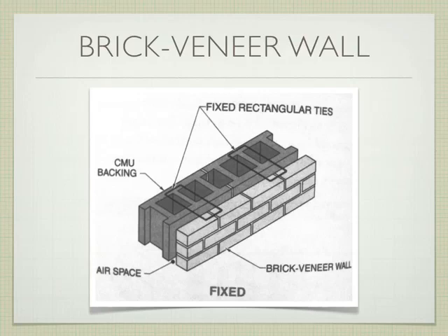The other thing that's really critical about this is that these bricks are not right up against the building. There's a little tiny gap of airspace that goes in between the brick veneer and whatever the primary structural piece of the building is. Why do you think that would be there?